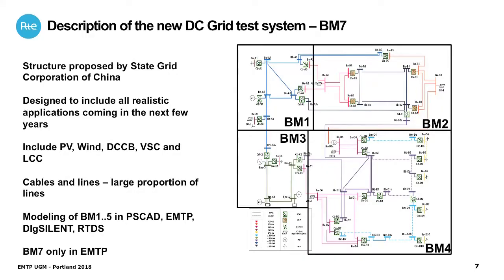BM1 to BM6 are smaller, and they are presently under development in the different software tools, so EMTP, PSCAD, DIgSILENT, RTDS. So not only EMT, because in the previous working groups it was only EMT simulation. Here it's also phasor domain tools.